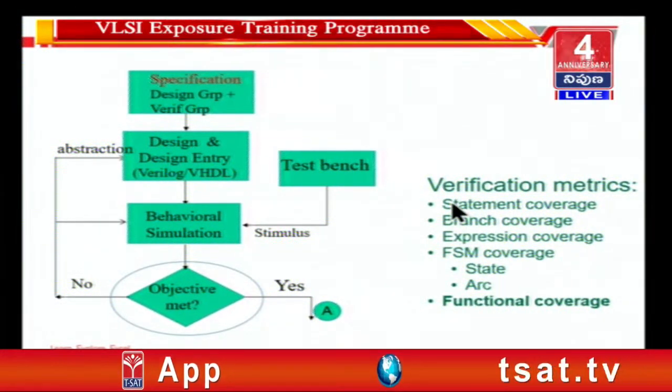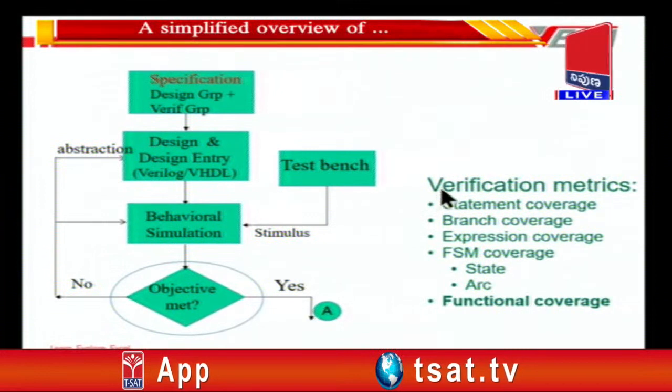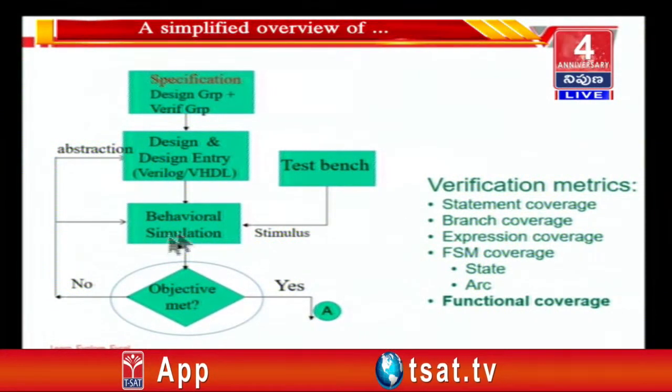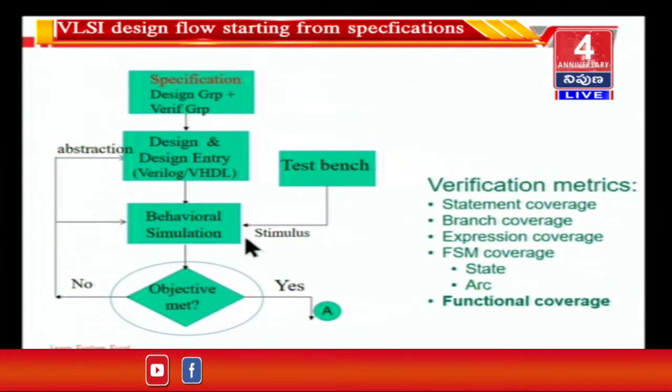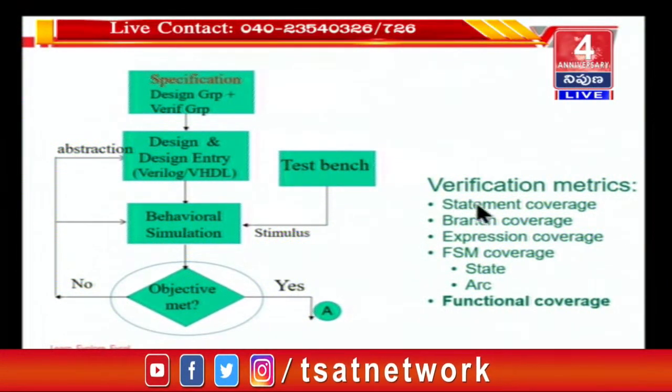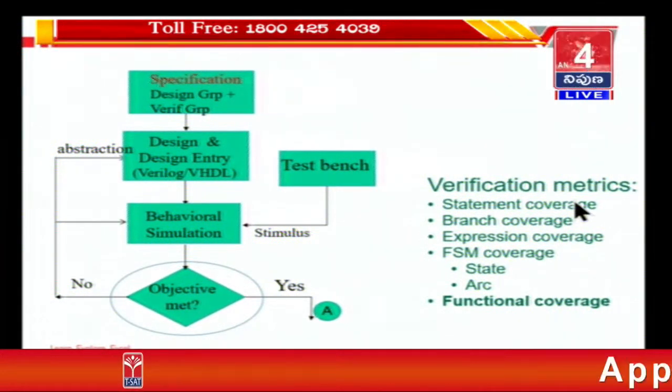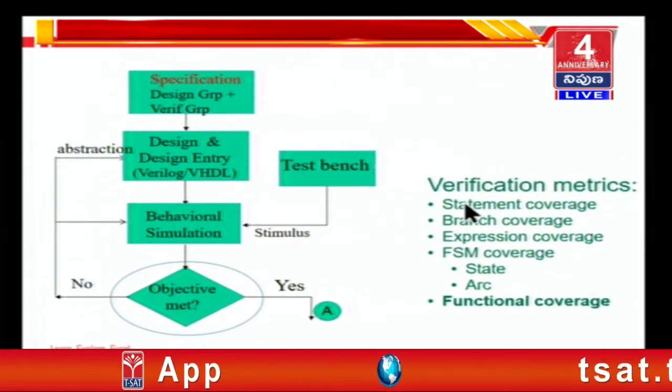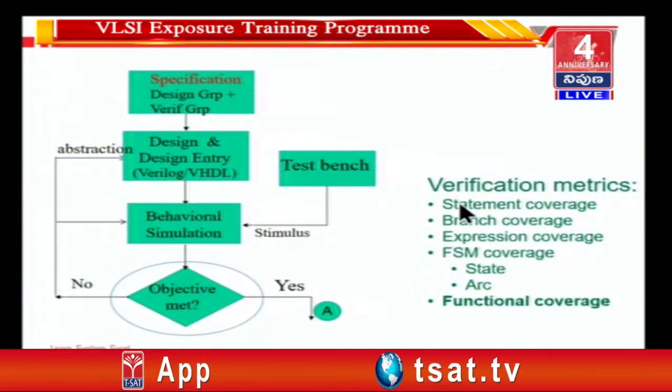Statement coverage. There are tools, the simulation tool, the simulator, will have a mechanism to find out how many times a particular statement is executed, if it is executed at least once or not. It is what is known as, you have to profile the code.